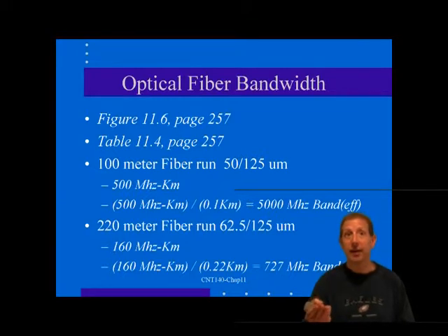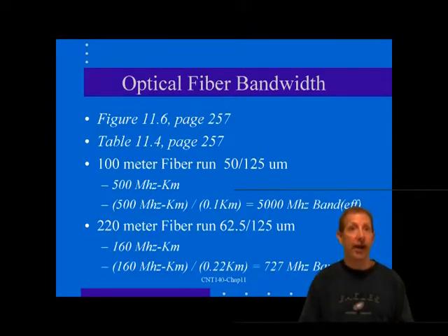Now, in addition, now that most of the equipment optics for high-speed networking are laser diode based, the assumed cost advantage of multi-mode friendly LED sources is essentially nil. So the problem is whether to specify less expensive, more common multi-mode fiber to the desktop, or to use single-mode fiber.